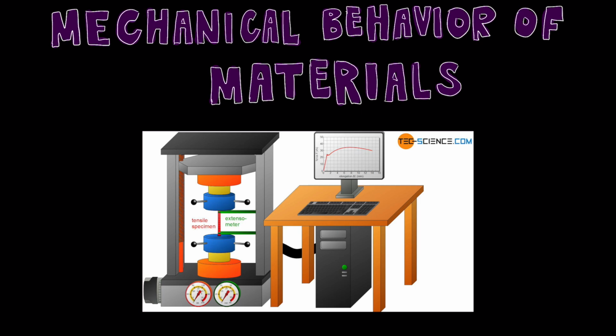In a typical tensile test setup, you'll have a tensile specimen, which typically is in the shape of what we would call a dog bone. It has a narrower center and larger ends, and that's to ensure that we know where failure is going to occur. It's going to occur where stress is highest in that narrower center.